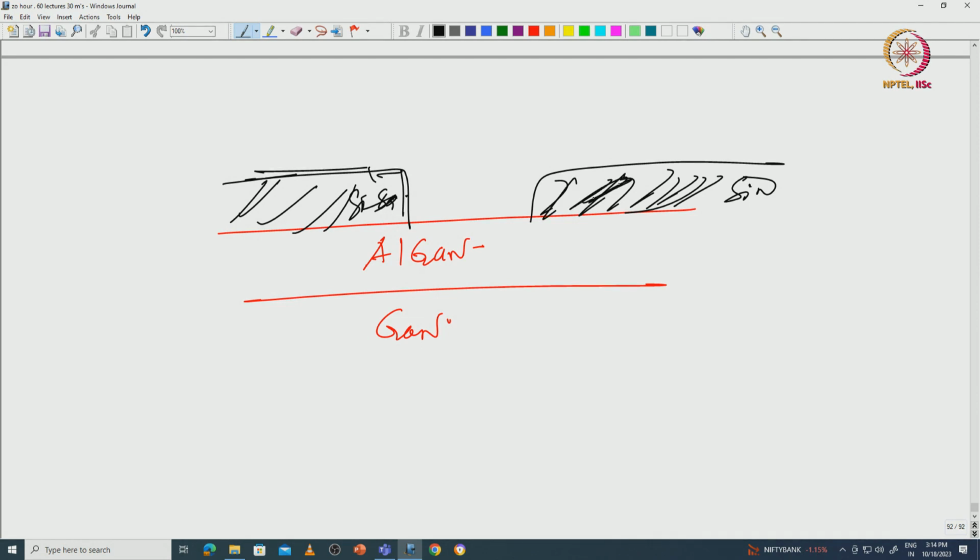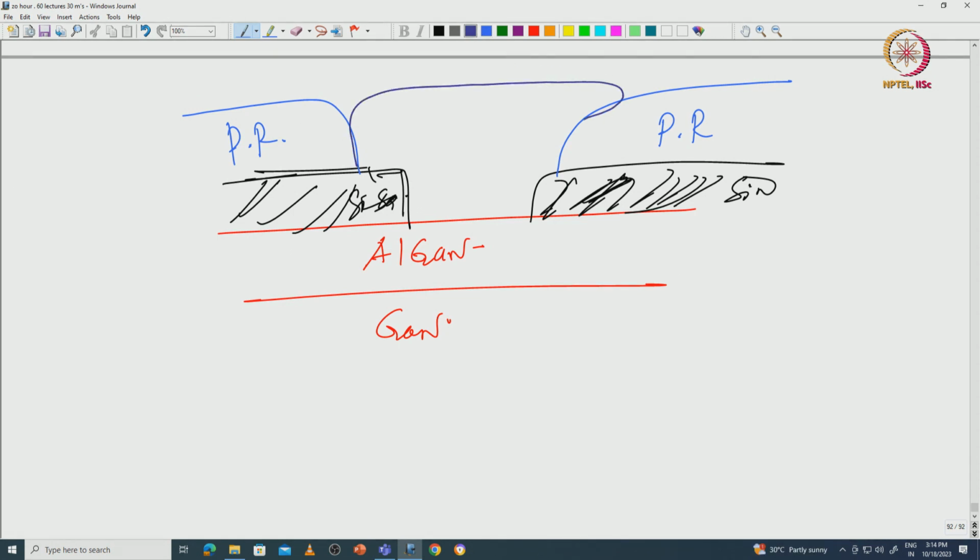Now you spin coat photoresist, correct? You spin coat photoresist and you define something like, say, photoresist is here. You define an opening like that. This is photoresist, PR, an organic material. Then you can deposit a metal now, something like that. It will come like that. This is a metal, nickel gold maybe, and you remove the PR now.